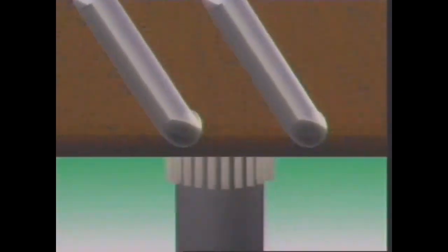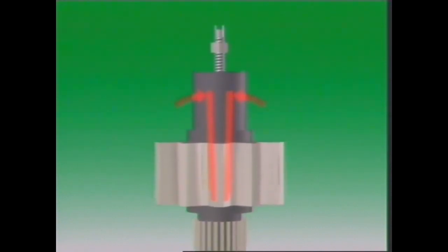The pitman shaft is supported by two caged needle roller bearings in the steering box housing. The sector teeth are angled, and an adjustment screw on the steering housing cover provides proper engagement of the sector gear and nut teeth.